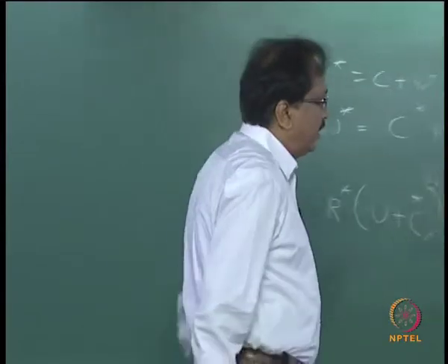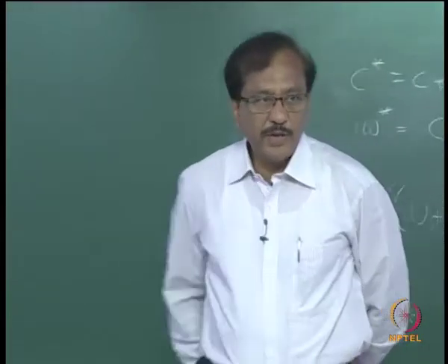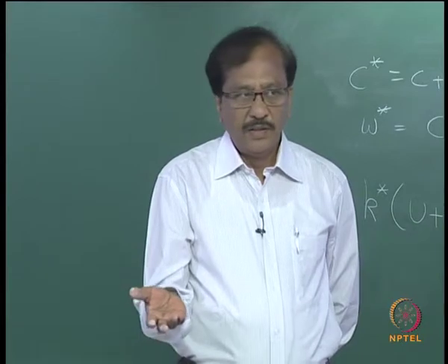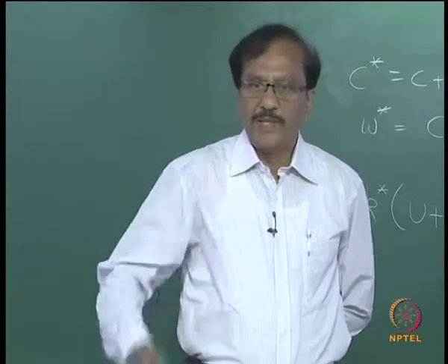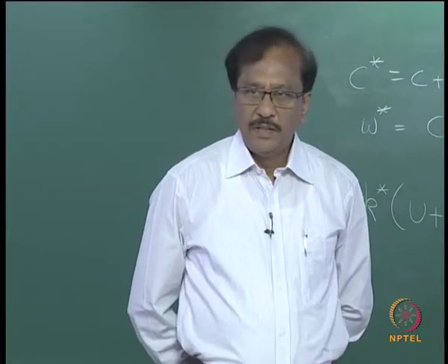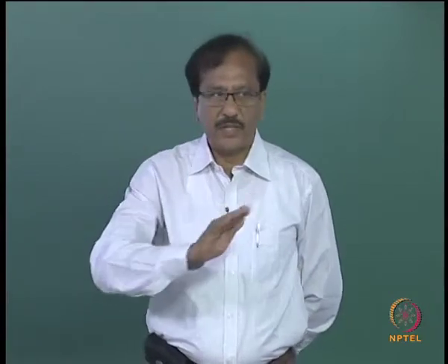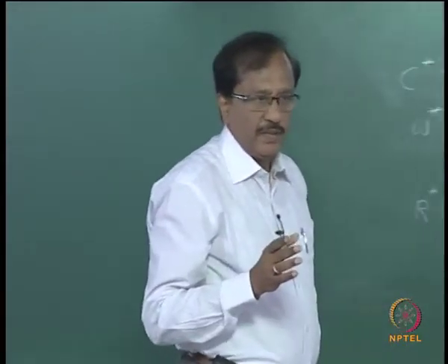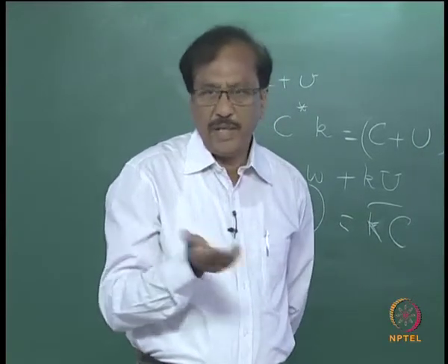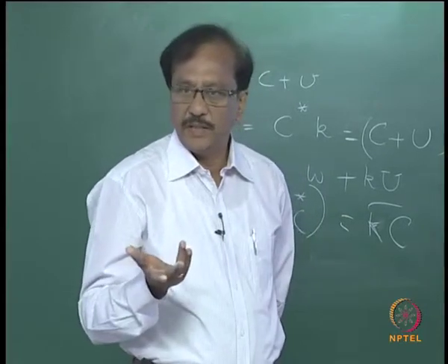Just imagine, if you have the tanh KD which is going to take care of the effect of water depth, then every time you need to deal with that variable. Herein we are trying to understand what is the effect of current on the wave characteristics. It does not matter, we consider just the deep water conditions for simplicity.